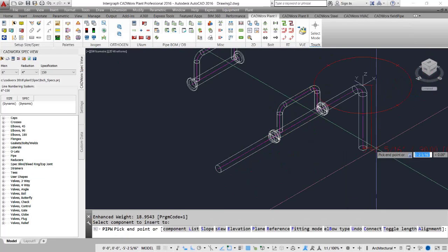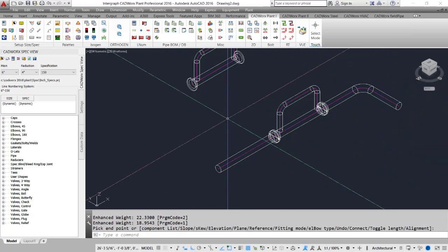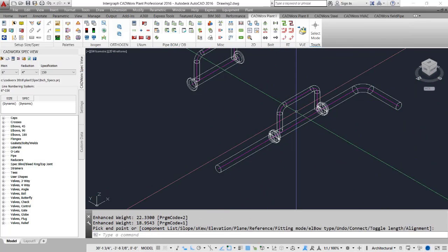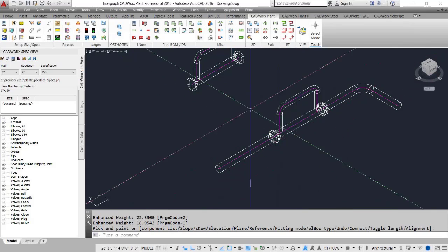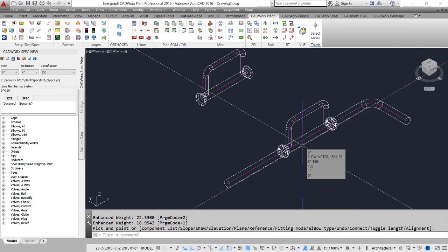So I'm picking my weld neck flange, and now that's ready to ISO. It's going to show up on our bill of material correctly, and it's not too geometrically rich. If I had gotten a vendor-provided solid for this, it might have part numbers engraved on it, a flow arrow, just unnecessary geometry that could tax my machine.